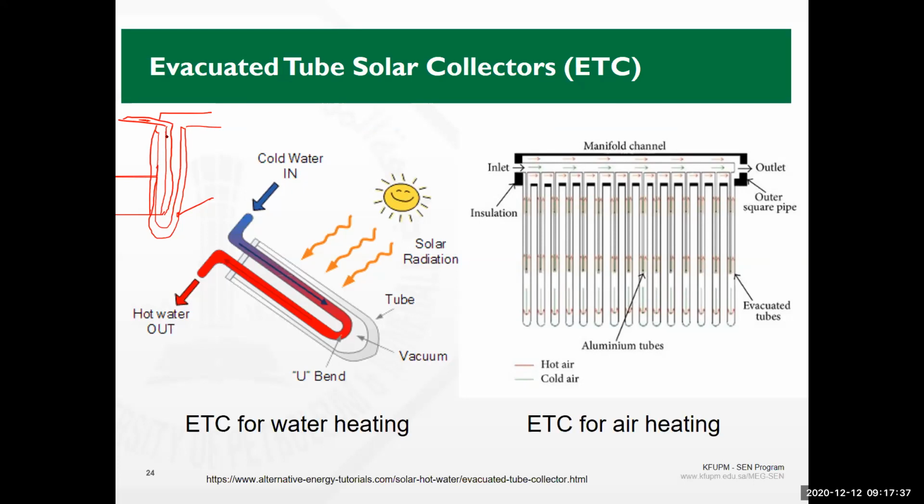So you have heating for the air as it goes down and goes up, because solar energy is directed here and it's passing through. This tube is made of aluminum. Sometimes you can have this tube painted black so that it gets heated. It heats the air as it flows down, and it heats the air as it goes up, and the hot air is leaving from here.